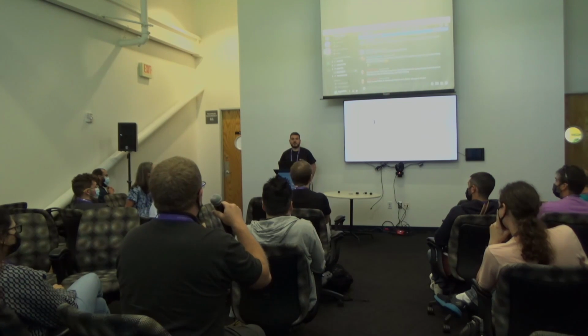Yeah, that's one thing. And the other thing is that with openAMP, you can do this messaging synchronization, like mailboxes between two systems that are actually running independently. So you can have a shared memory where one system writes data and just pings the other one that the data is there. And of course, it maintains all the atomicity and cache coherence between the systems and all that stuff. So yeah, that's basically that.